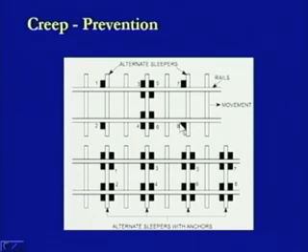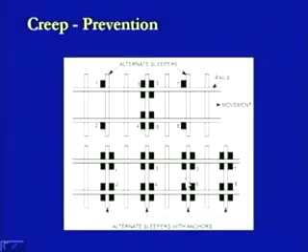and then there is another anchor which is placed at this location. Now, another way of doing the same type of thing is that we have the anchors placed at all the locations, because there are chances of the creep getting induced in both the directions of the movement. Therefore, the anchors have been provided in this direction as well as in that direction, and again these anchors are provided on all the alternate sleepers, they are not being provided continuously.